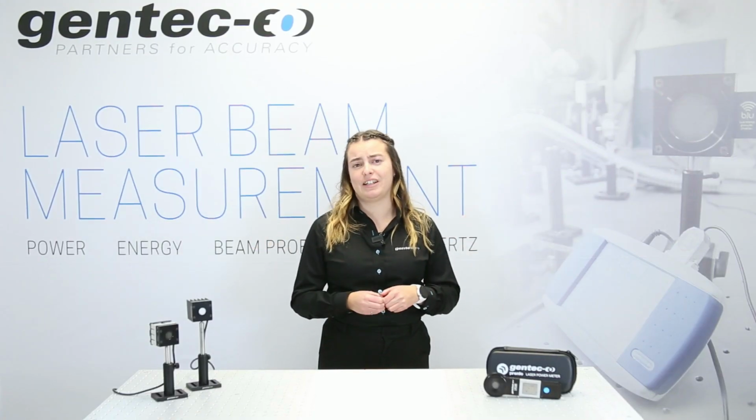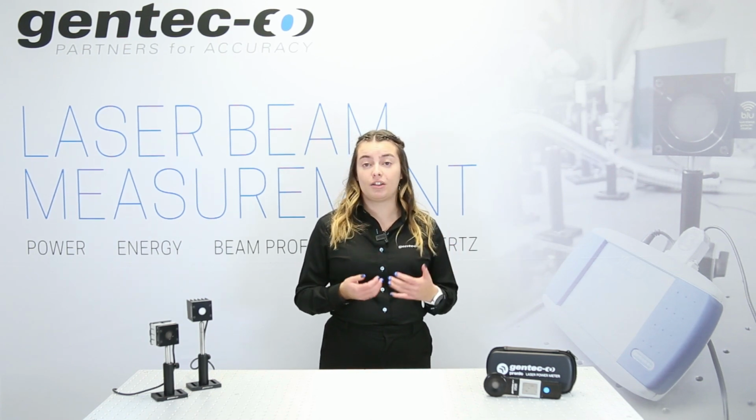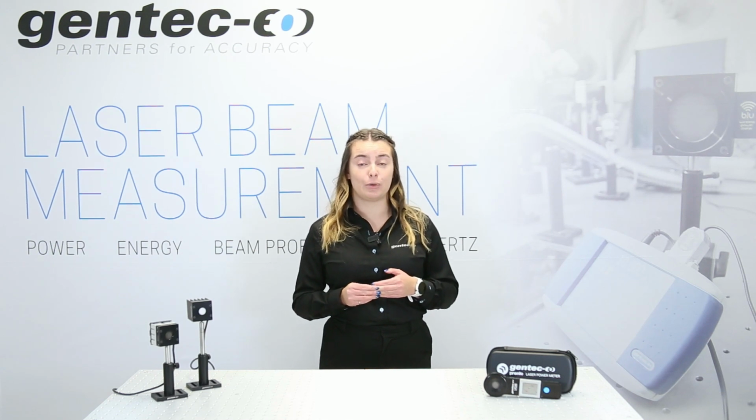Average power is a good place to start. You can see this parameter as the strength of the laser. The more powerful the laser, the deeper it can cut or weld metals. Therefore, adjusting the power to the correct level will make sure that you are able to complete your laser process and that you don't waste too much electricity or damage the piece with too much power.